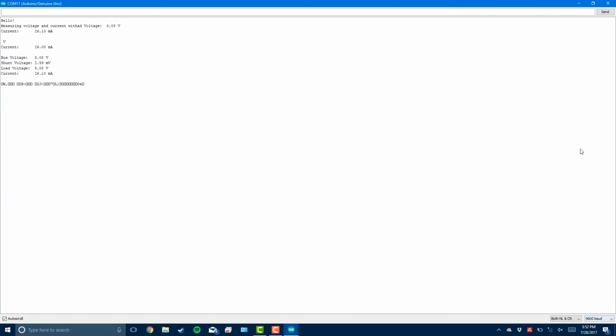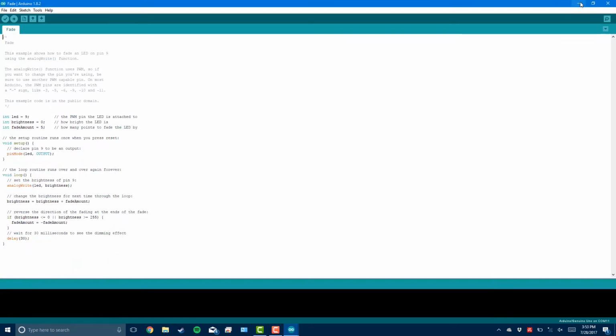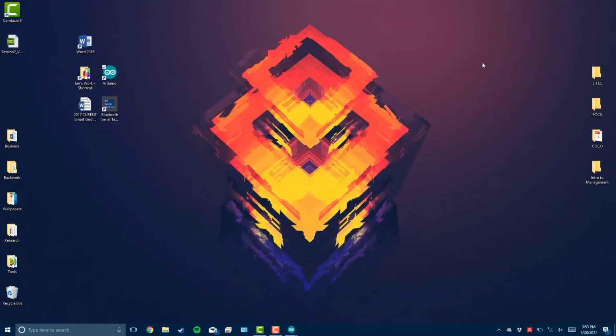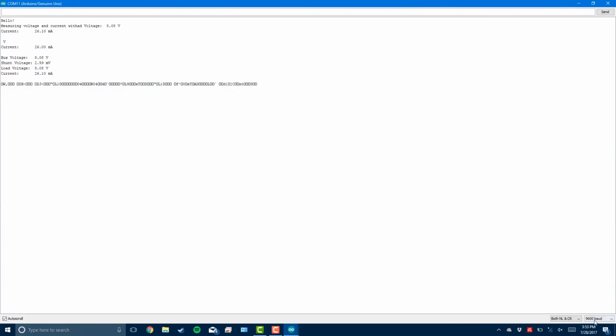Looking back, the baud rate here is 115,200. So when we're doing serial monitor, let's go to that. Where is it? Right here. We have to change it to have the exact baud rate.